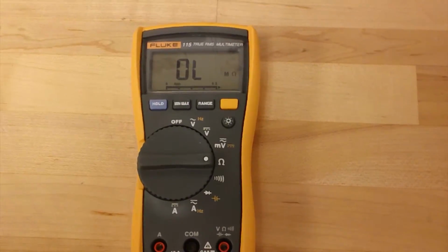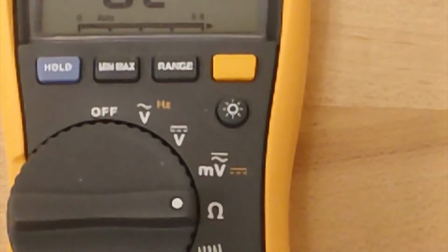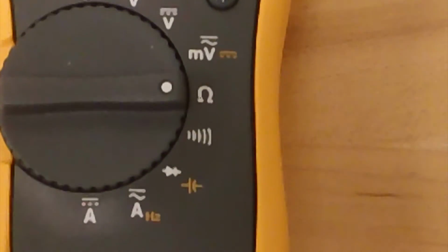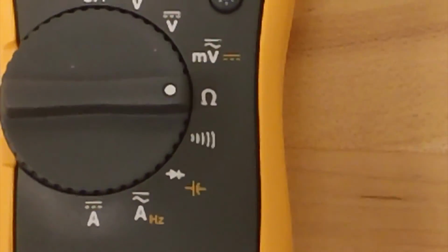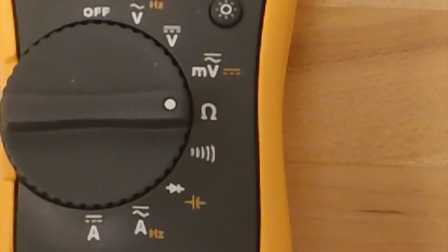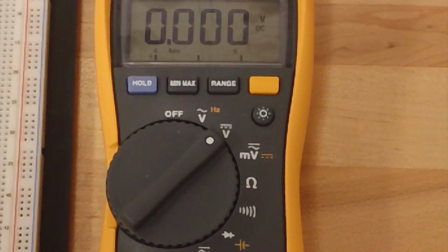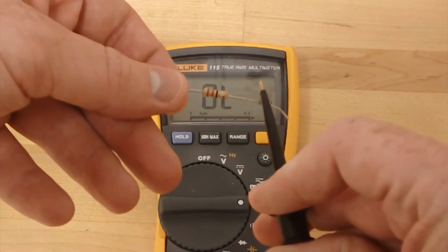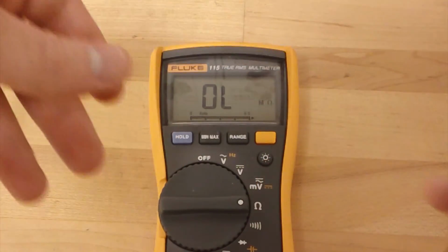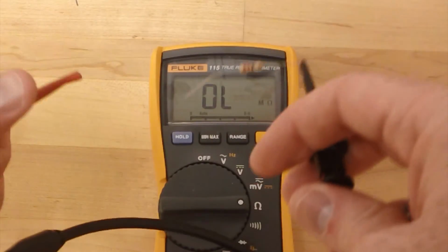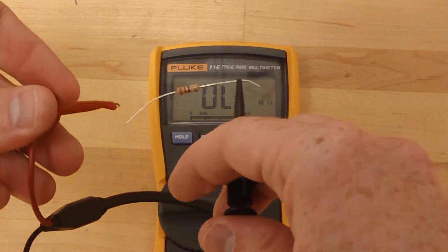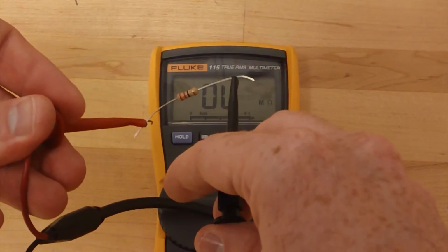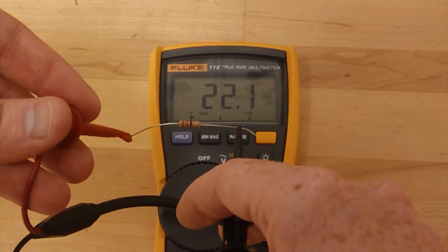Voltage measurements are vital to understanding why an electrical component is or is not functioning properly. Voltage is measured in parallel to the circuit. In this lab, we will only be measuring DC voltage, represented on this multimeter with a V and a straight line next to it. Similarly to voltage measurements, resistance is measured in parallel to the resistor. However, it is recommended that you measure resistance while the resistor is not connected in the circuit. Measuring resistance is a fast way to check that you are using the proper resistors for a circuit.